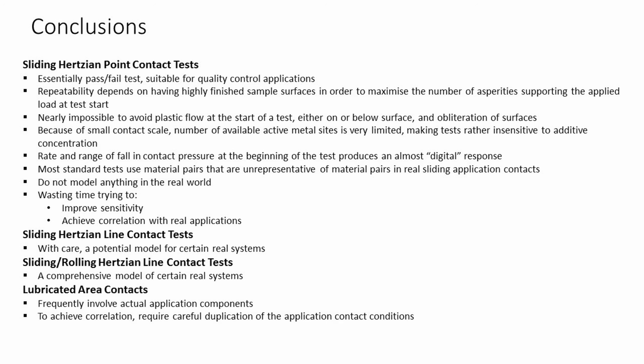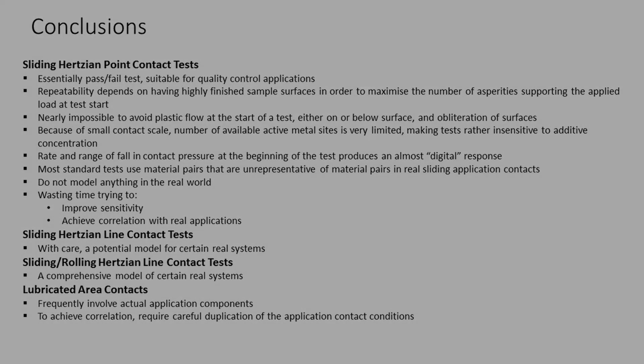Sliding Hertzian line contact tests, with care, do have the potential to model certain real-life contacts. With regard to lubricated area contacts, these frequently involve actual application components. To achieve correlation requires careful duplication of the application contact conditions, in particular when it comes to lubricant entrainment.